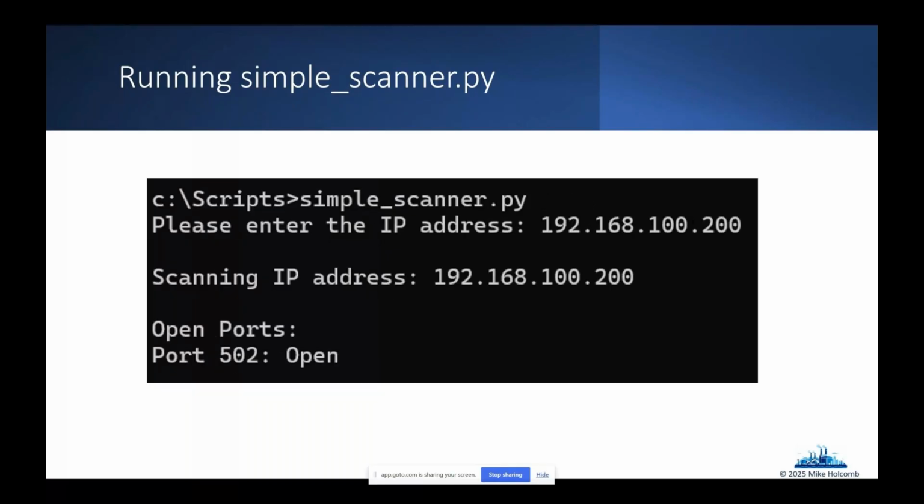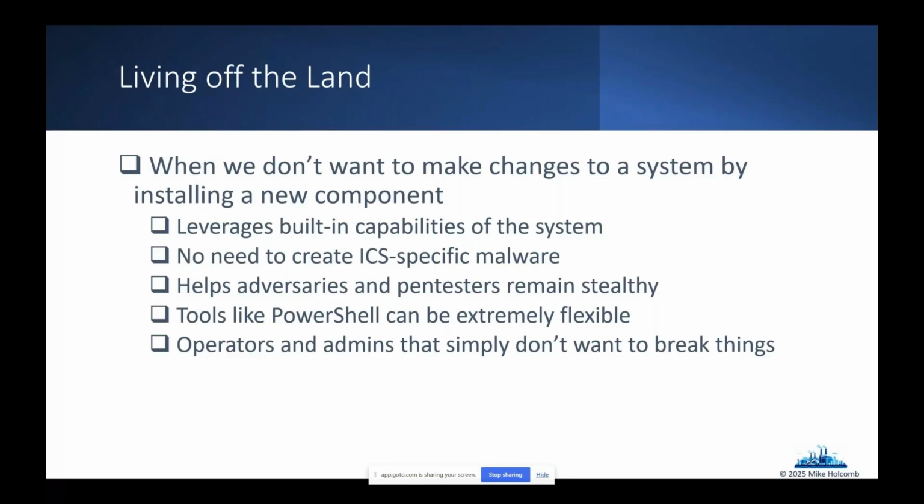And then I can run it against a PLC that I have. And you can see in this case, it says TCP 502 is open, which means more than likely that's going to be Modbus. So we have a PLC sitting there. So again, it's just a very simple port scanner just to test those few ports. So nothing fancy. When we start thinking of, okay, well, what if I am an attacker?